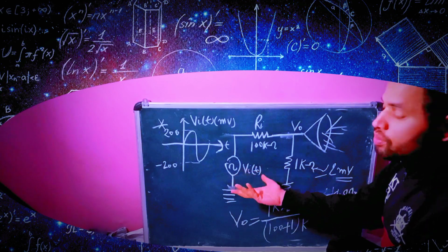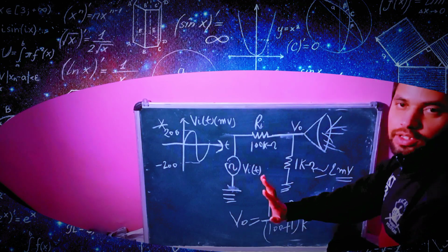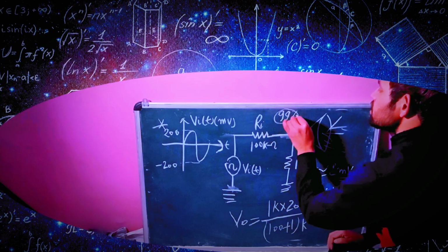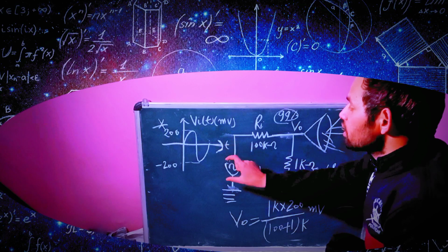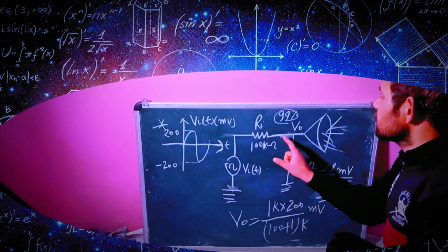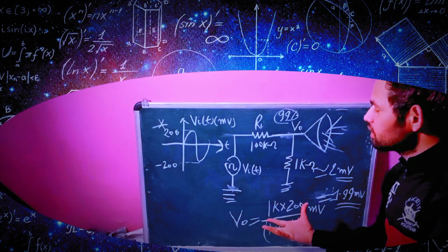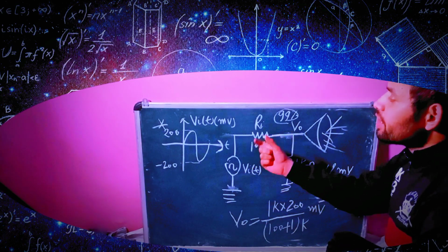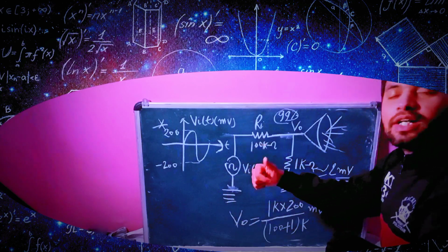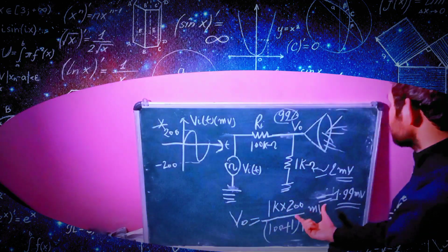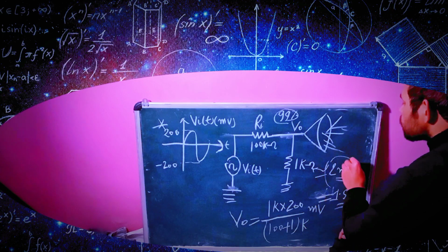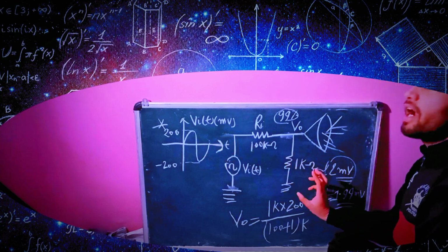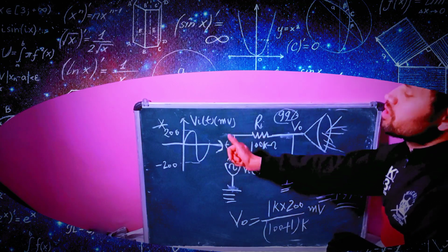So 198 millivolt has been attenuated. If you see how much attenuation there is, it is 99% if we connect the input voice signal directly to the load, without any amplifying device. That is why we see the important role of the common collector amplifier, which is the emitter follower. You see how much reduction there is. 2 millivolt means we are getting a negligible amount of strength of this signal at the load, and we are not hearing any sound of the input signal.